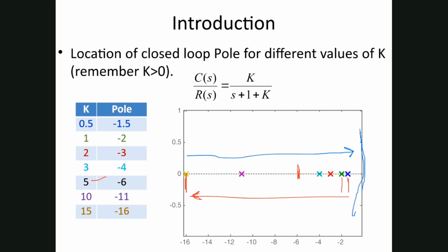Is it clear how just increasing or decreasing the gain K can alter the position of the poles? So is it okay that your gain K can dictate the pole locations? We have also seen that if we increase the value of K, your poles go deeper into the negative side of the s-plane, and if we decrease K, your poles go towards the imaginary axis.